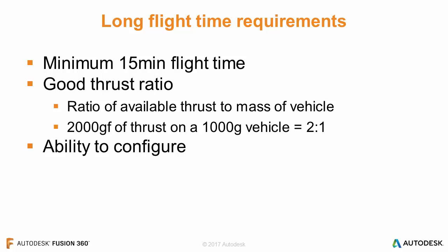The higher that ratio, the quicker it can maneuver, but generally you're going to be drawing more current and you're going to reduce your flight time. So we're going to have to explore our options, and there's going to be some give and take to plan out what our maximum flight time while still keeping it agile enough to get to our areas quickly and maneuver into tight spots. We also want the ability to configure.